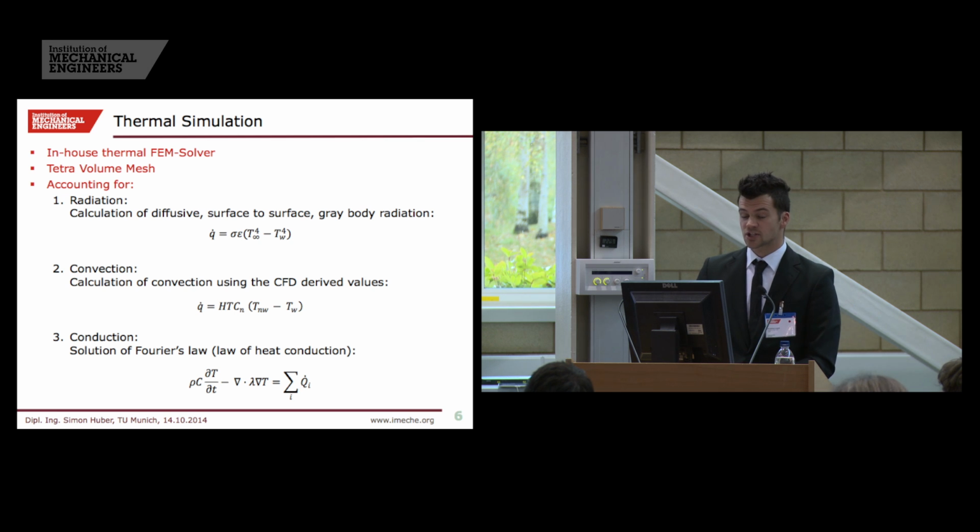The thermal simulation is an in-house thermal FEM solver. We're solving on a tetra volume mesh, and here we are considering all three types of heat transport. The radiation is considered as a diffusive gray body radiation.